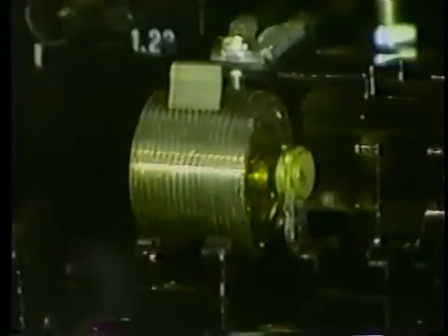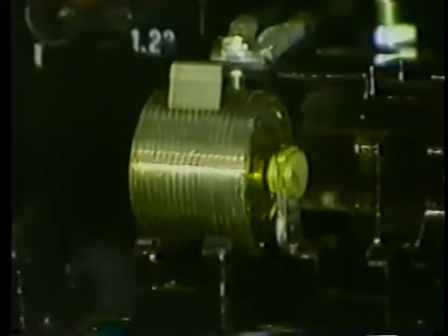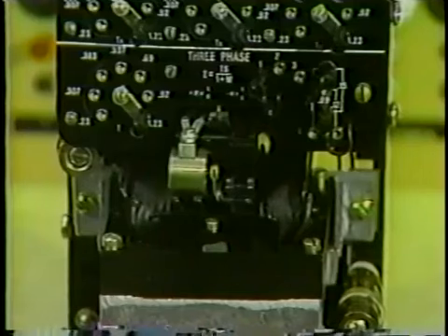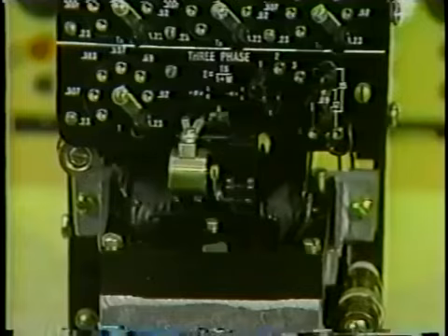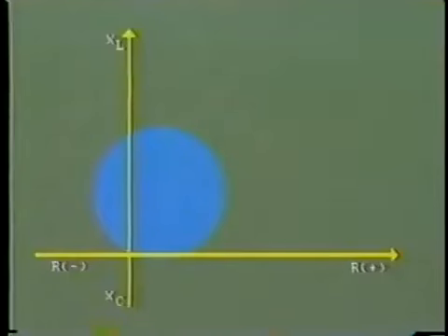The Moe relay is typical of the improved type of distance relay. Instead of the beam, this uses a cylinder moving within a magnetic field, similar to the directional overcurrent element. Coils are wound around the electromagnet, and these are fed from the CTs and VTs of the primary circuit. The circuitry is designed to give the relay specific characteristics, as shown by this circle diagram. The relay will operate if the measured impedance from the point of origin falls within this circle.